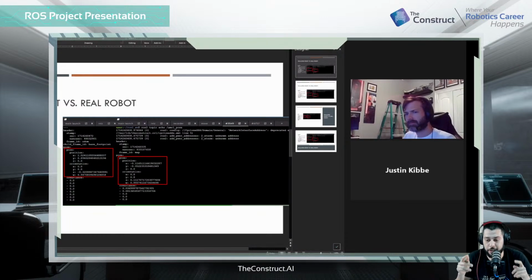The odometry topic is just the messages from the encoder of the motor, telling you the clicks that it has done, and it just spits it out right there. And AMCL, on the other side, the odometry frame, you define that when you launch your controllers with the robot state publisher, which is basically where you define the relationships between the wheel of the robot and the scanner, so you can do all these navigations and the TF tree.